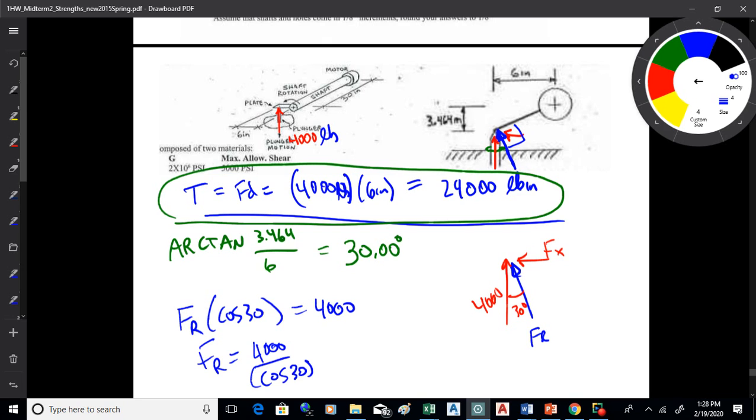That will get you that resultant force, which is perpendicular to the moment arm, so you need to also get that distance there, and then do the torsion as force times distance. So you should be coming out with about 32,000 when you do that to get the torsion. Both of these numbers, using those methods, are wrong, and you should end up with 32,000.